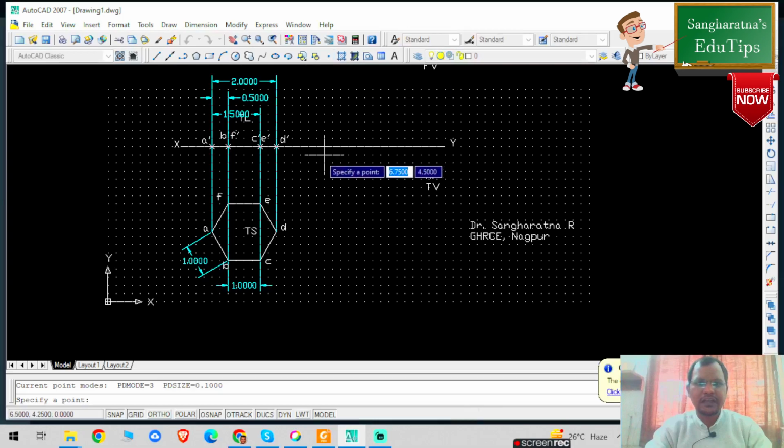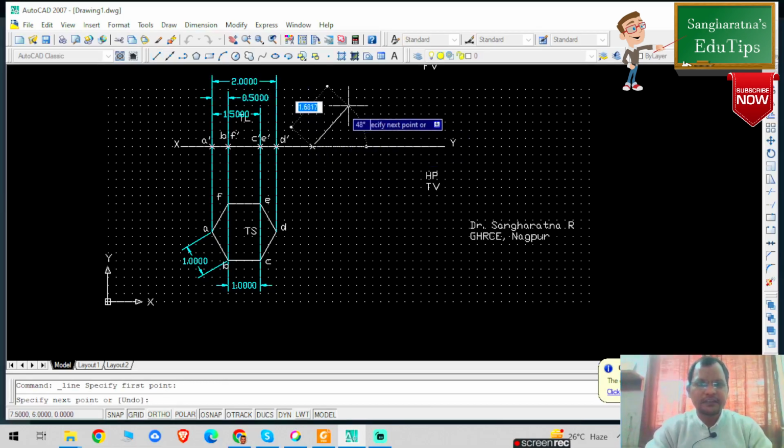So I'm selecting any random point on this particular XY. Okay, let us say this is my point A dash. From this particular point I need to draw a straight line, right, which will be inclined at 45 degree, and the length will be 2 AutoCAD unit. You can check, this is 2 AutoCAD unit length. So I'm going to select 2, that is 2 AutoCAD unit, and then press tab, and the rotation angle is 45. Then press enter, then press escape.